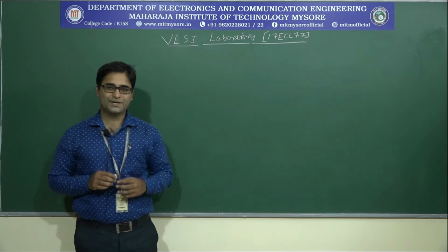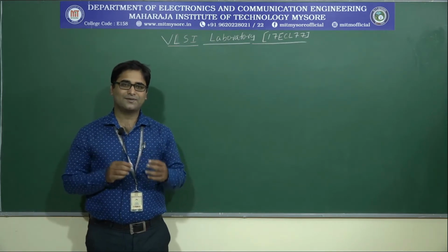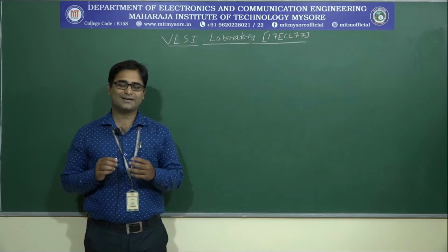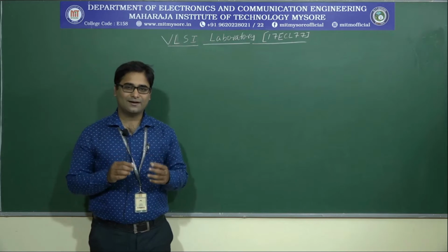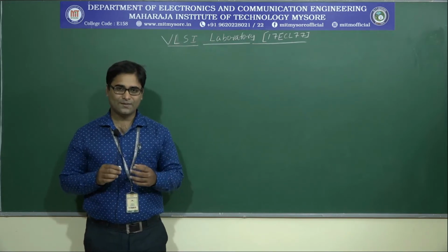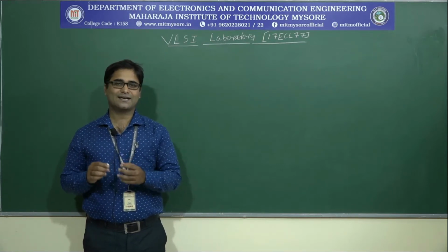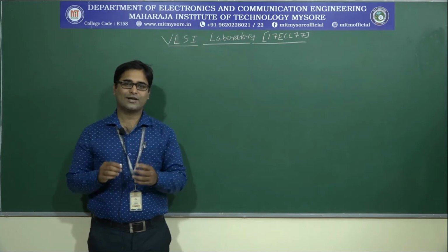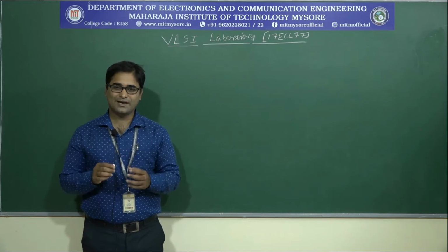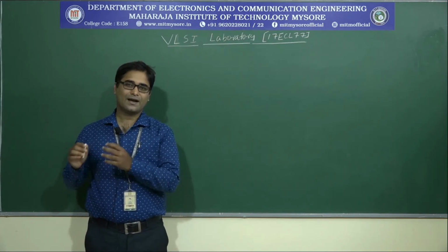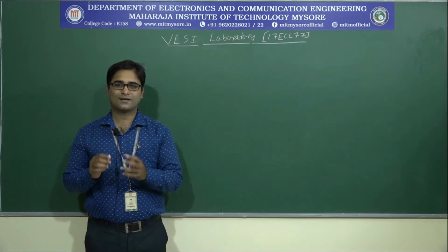We will see the course objectives in the VLSI lab. It deals with the computer aided design tools, or CAD tools. We will be seeing the custom IC design flow. We will learn what we mean by DRC, design rule check, and LVS, layout versus schematic, and we will design and simulate the digital circuit, and also we will design and simulate the analog circuit.